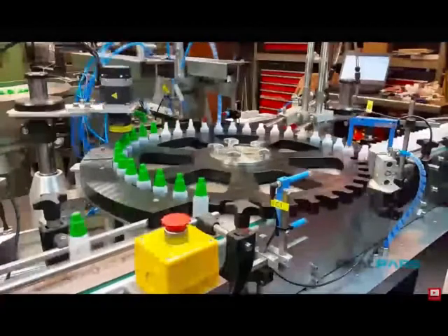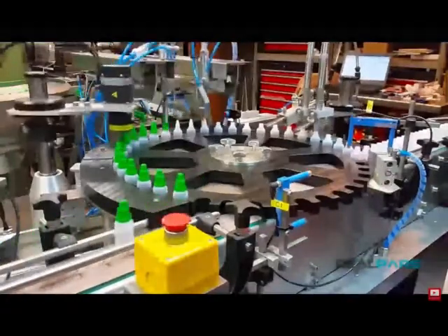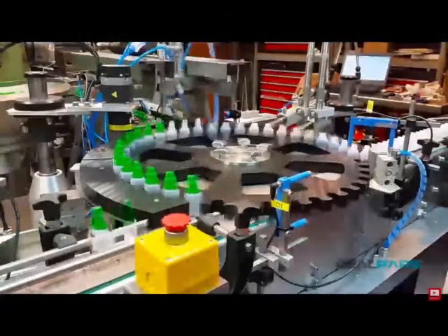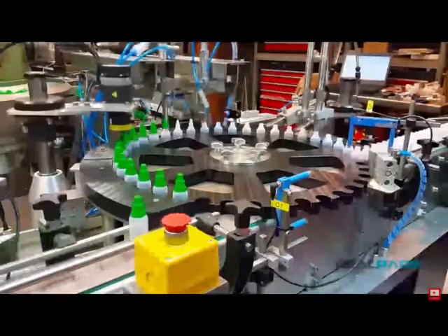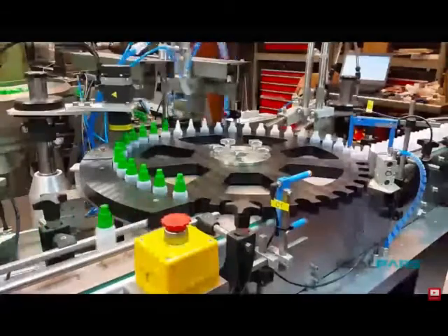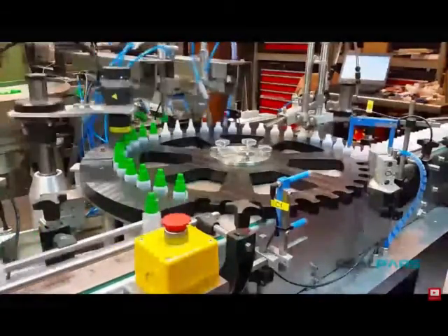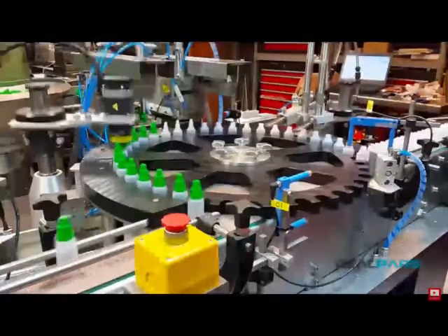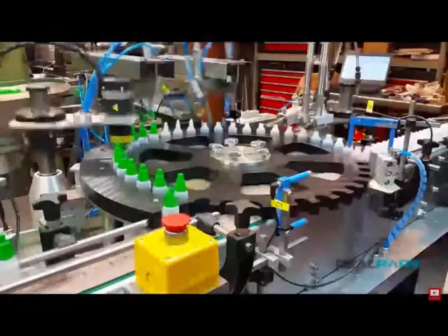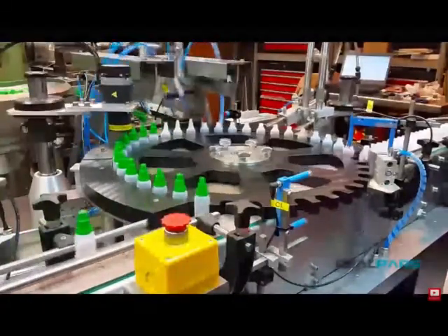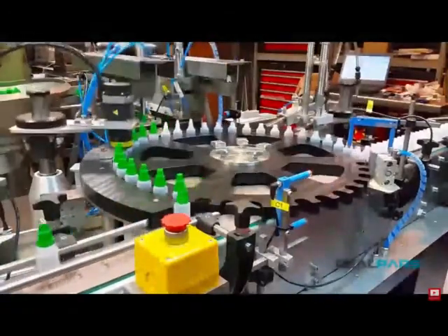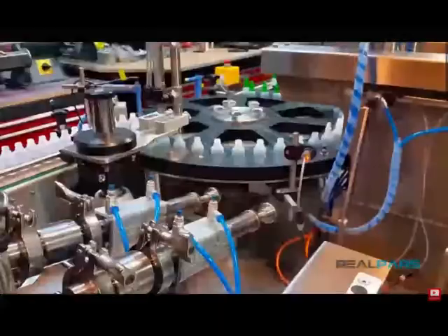Let's first discuss an assembly process that would place a cap on top of a bottle. The procedure to attach that cap may be by compression, meaning that the lid is pressed onto the bottle, or the lid may be twisted or turned onto the bottle. This automation process would take that bottle into some sort of piece holder, while another piece holder would hold the cap. The automated process would attach that cap to the bottle in a single action, either by pressing the parts together, or one of the piece holders may spin in order to twist the cap onto the bottle.